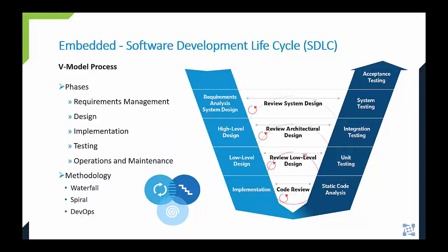With these standards that I just mentioned, you will find a V model diagram, and it expresses each of the software development phases that need to be performed in order to achieve a maximum safety level assurance. Here's an example of the V model graphic. It captures the software development lifecycle phases that embedded safety and security critical systems need to go through.